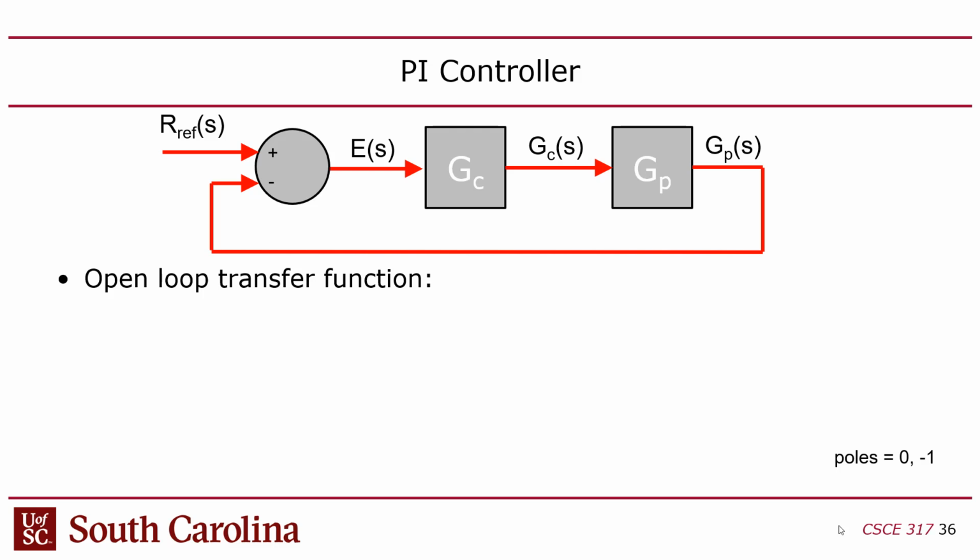Okay, so then if I have a PI controller, you can create an open loop transfer function, which is just that ratio I showed you multiplied by the plant model, right? So what is my plant model? Well, remember, this is the transfer function for the coin. It was 1 over m, where m was the mass of the coin, over S times S plus B over M. B was the coefficient of friction of whatever material I'm dragging the coin over, the robot's pushing the coin on, carpet or floor, right?